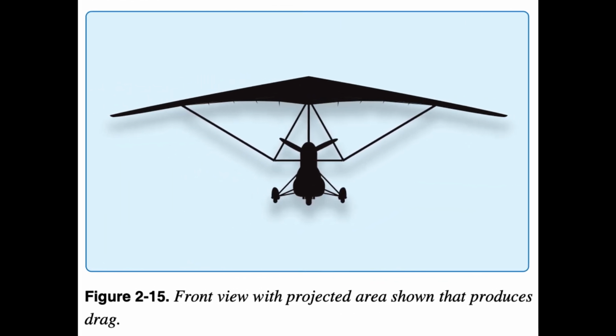Drag. Drag is the resistance to forward motion through the air and is parallel to the relative wind. Aerodynamic drag comes in two forms. 1. Induced drag, a result of the wing producing lift. 2. Parasite drag, resistance to the airflow from the carriage, its occupants, wires, the wing, interference drag from objects in the airstream, and skin friction drag of the wing.